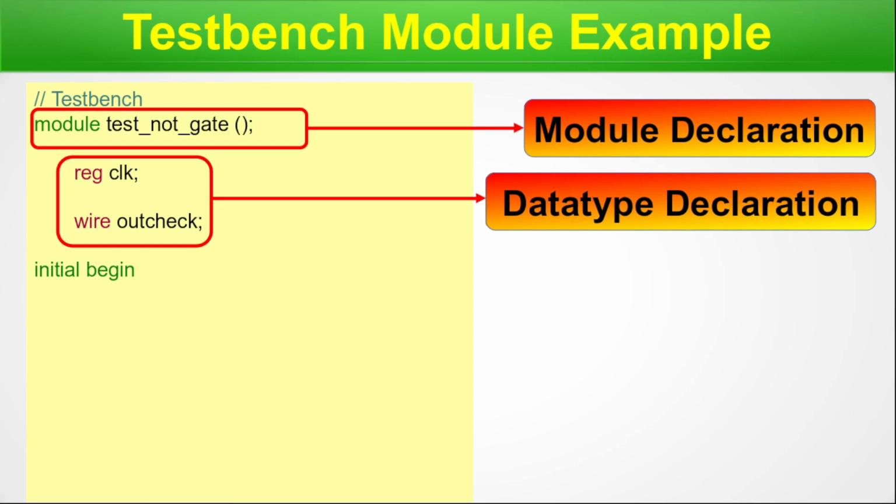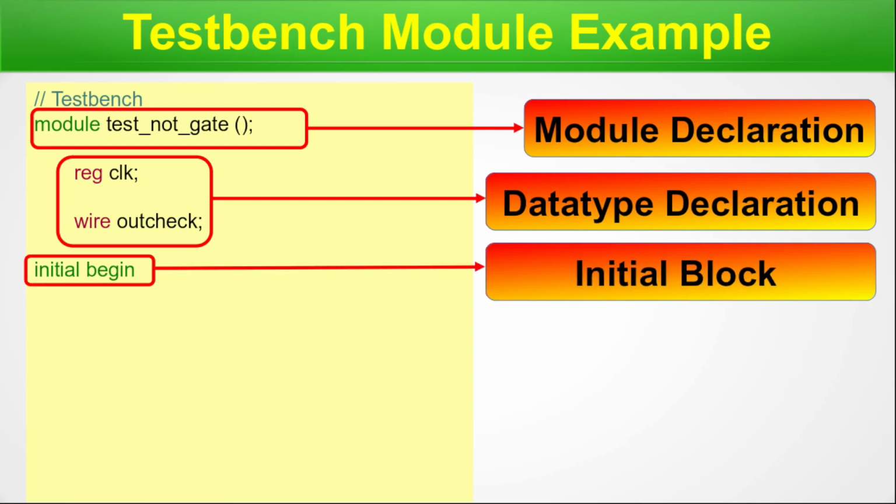Initial begin. This is an initial block. We are starting the block, and whatever we write after this line comes under the initial block. So the begin keyword means we are beginning the initial block. And we write here $dumpfile abc1.vcd. VCD is value change dump. In the hands-on episode, I'll show you how to open the VCD file in a viewer. Then $dumpvars. This system command dumpfile opens a file with the name abc1 and the extension VCD. And in that file, all the changing variables with respect to time, including the time variable, get dumped by the next system command, dumpvars.